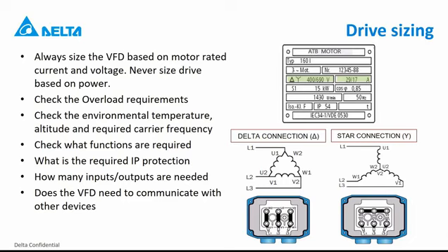Also important to check if the drive actually has to communicate with other devices and what communication protocol needs to be supported. And also very important is to check if there are any requirements from the application in terms of total harmonic distortion or electromagnetic compatibility.